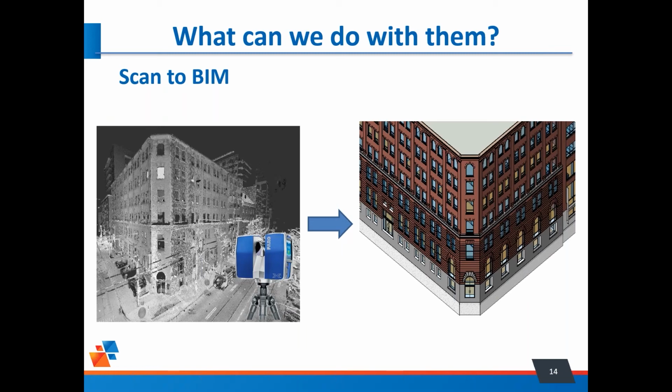I'm going to use the point cloud data to import it into our CAD software and model a building information model from that real world data. So inside of Revit, we can cut sections through the point cloud, elevations, align the building elements with a lot of precision. So the point cloud comes in, I can cut through it, and I'll show you a little bit more of that when we get in, and I'll show you some examples of what we've done in the past.